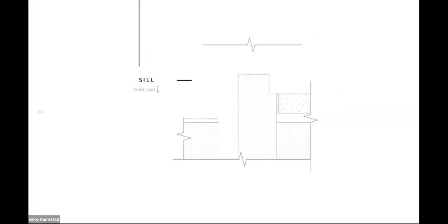At the sill, we have, again, let's say a knee wall, a concrete knee wall that receives its control layers, thermal and air and water barrier control layers. On top of that, we have the sill anchor. Again, it's very similar to the T anchor I showed. Usually the slots on this one aren't meant for vertical deflection. They're meant for being able to shim and level the system. So the slots are usually a little bit smaller there to provide some tolerance in the field. This one is anchor bolted into the concrete, and we would work through all of those connections and have that completely engineered.